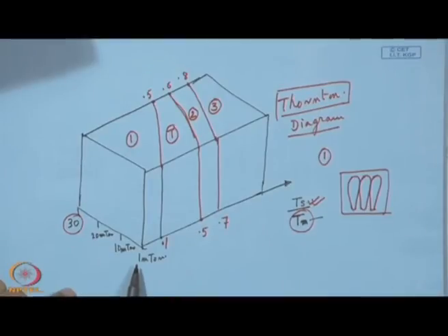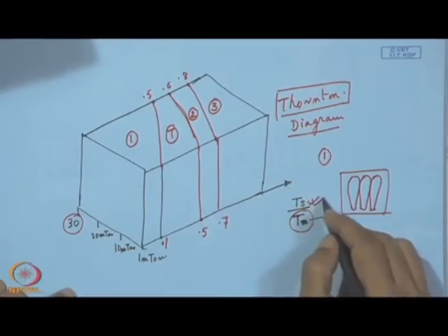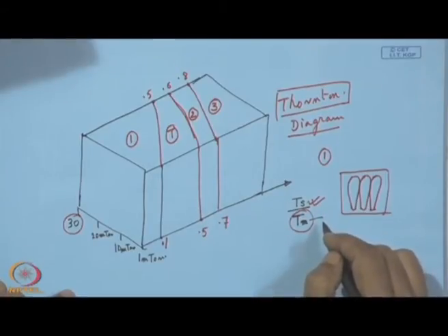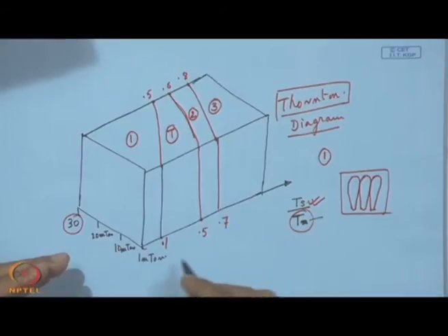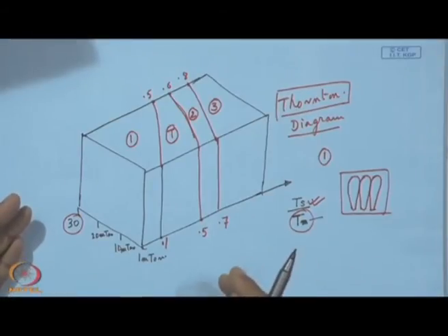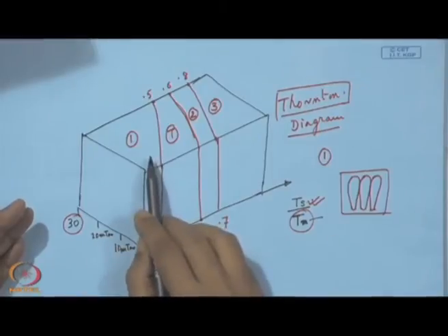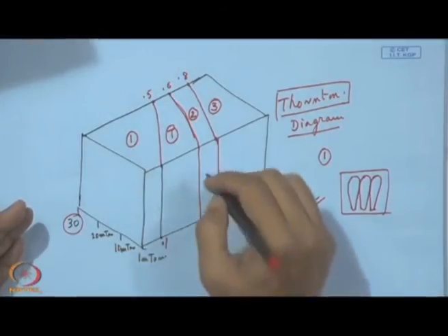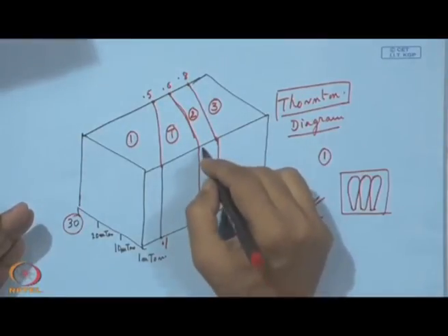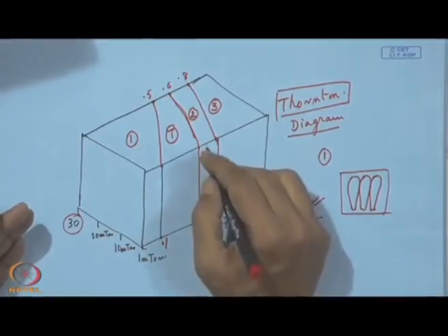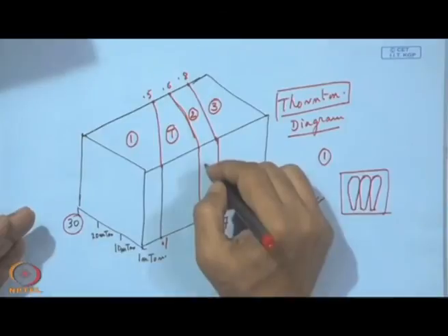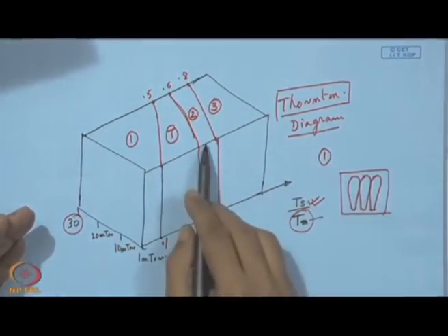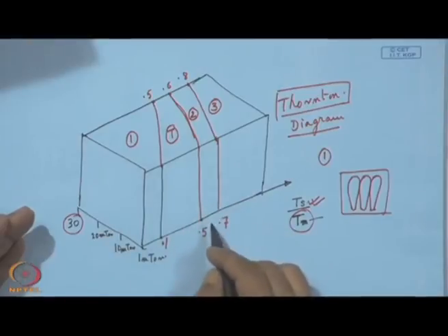So, this way we understand that on one side it is the temperature of the substrate, which should be at the low end considering temperature sensitiveness of the substrate, and at the same time the capability of the apparatus to work with a low pressure. Now, here what we have is a transition between 1 and 2. Now, what we have in zone 2, these are also sticks, but finer in size and densely packed. So, a transition from porous to densely packed starts within that.